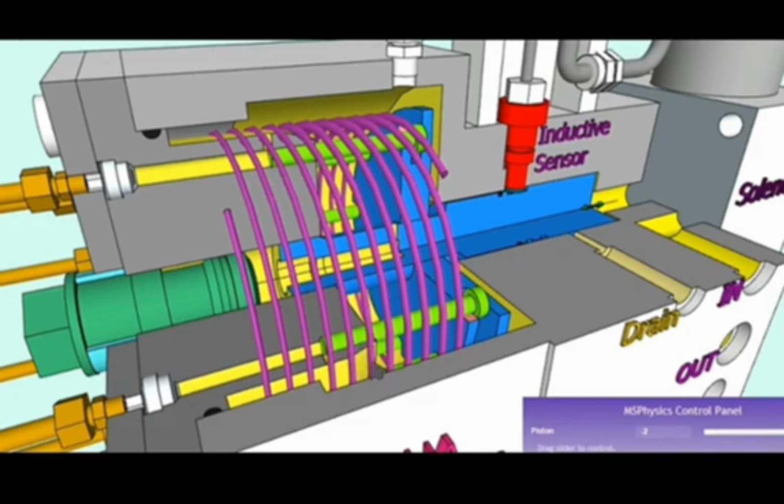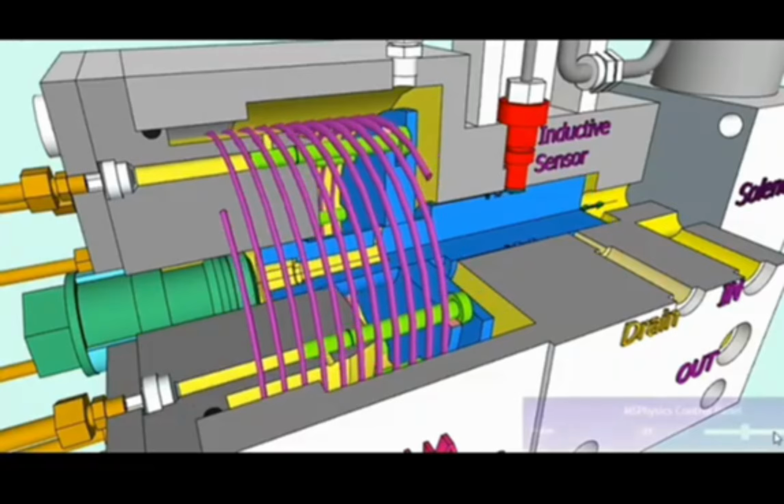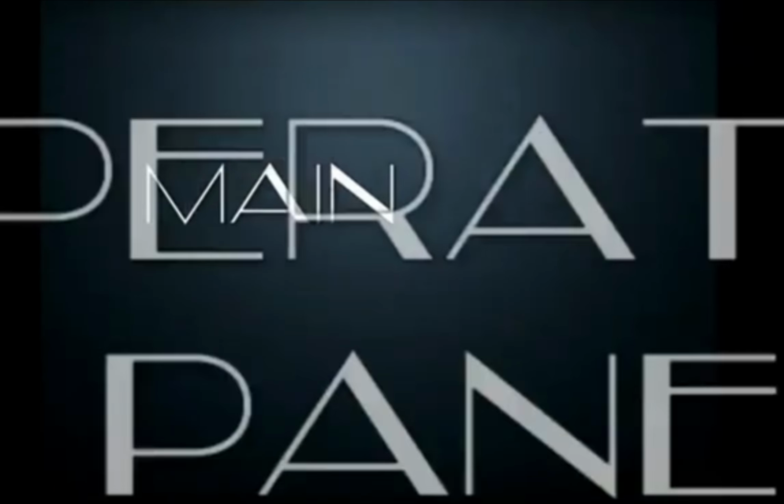This is the way this alpha lubricator is working, and this is very similar to the alpha lubricator which is normally used in MC engines. In MC engines we are using a separate pump for making the high pressure oil, but here we are utilizing the same high pressure oil from the HCU unit. And this is a small animation, you can easily understand.